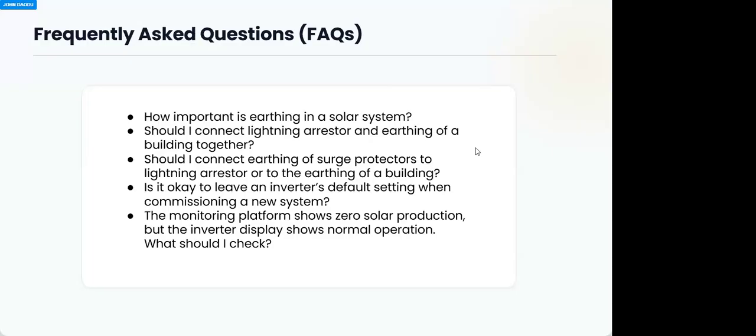When solar is going off, the bulb should come on, taking power from the battery, because the charge controller is connected to the battery. So that may be around that. But if you say it is charging properly and is showing these readings, you may be talking about the external load that is supposed to be connected to that port. Because you did not connect anything, you'll be seeing zero current and all.